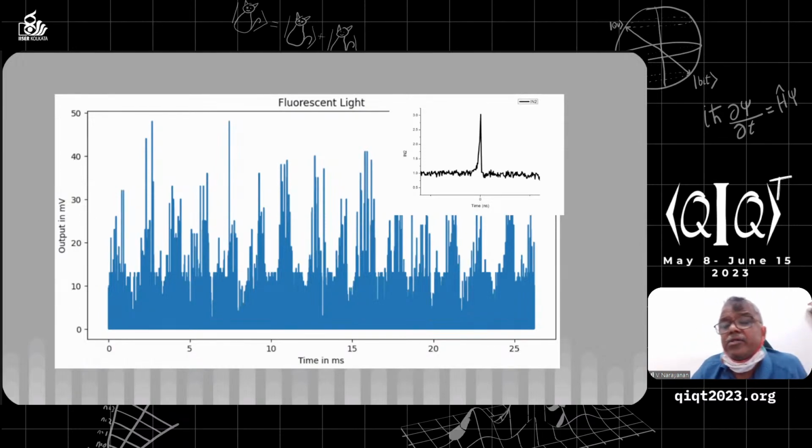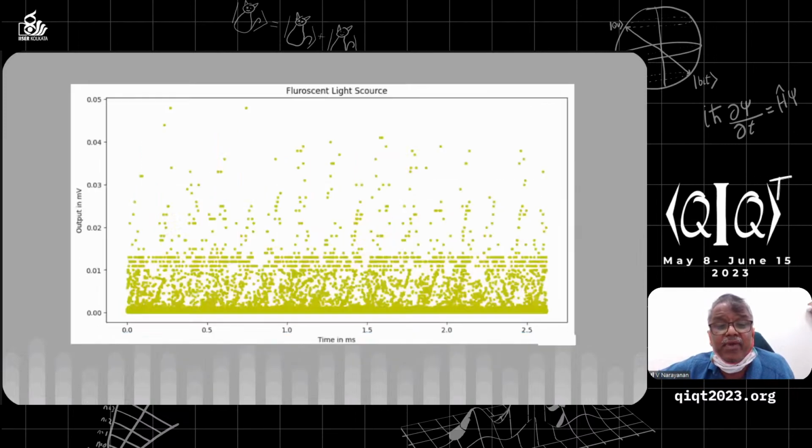On the top right-hand corner, you can see it has a pulse width. It typically produces of the order of 30 to 40 nanoseconds. So each hit produces at the output of this SiPM or the MPPC a pulse whose width varies in nanoseconds. Sometimes you may also have a double pulse, so one has to do a very careful selection of the pulse height and width, a very careful filtration. So one writes a kind of Python code. Those who are the young ones or the summer students do it very well.